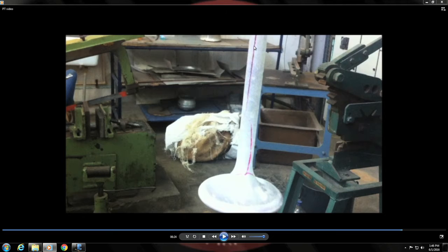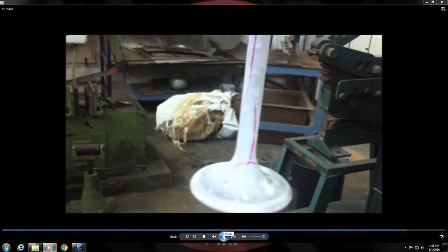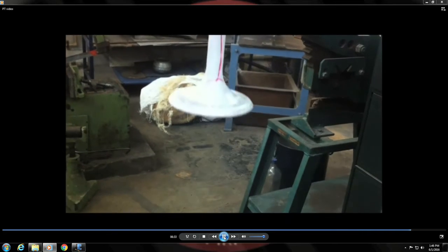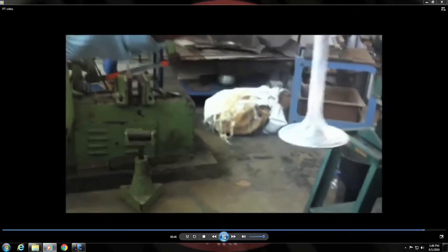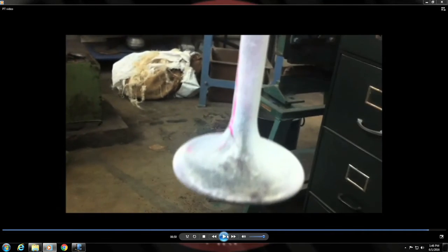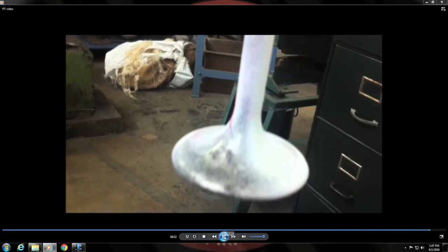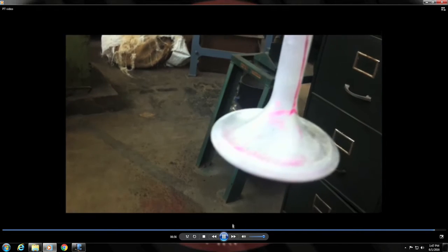Okay. So, that means this part is defective, there is a big crack across this handle, and here near the base also you could see there is a crack. Okay. Let us see if we could see any more defects. Yeah, so this is a closer view, you could see the crack, some indications over here also. So, that means there could be a crack in this portion as well. And there are some indications on the base here.